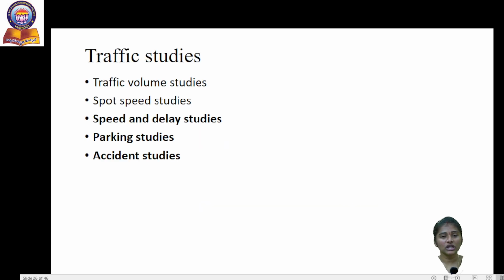Today we are going to discuss traffic studies. Traffic studies are generally conducted to regulate the traffic, and the main aim is to reduce the number of accidents. In the last video, we discussed traffic volume studies and spot speed studies. Now, in this video, we are going to discuss speed and delay studies, parking studies, and accident studies.